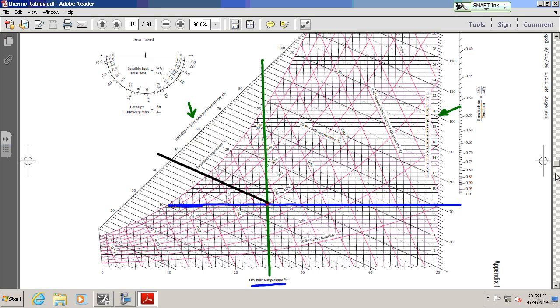If you went all the way up to 100% humidity, all the way to the top, your enthalpy is probably somewhere in the neighborhood of about 76. So from dry air to very moist air, your enthalpy can go from, in this case, 30 to 76. That's a pretty big range, right? That's why it's an important factor. You can't just throw it out typically when you do HVAC. Everybody see where I got that one? Pretty easy to read. We're good?